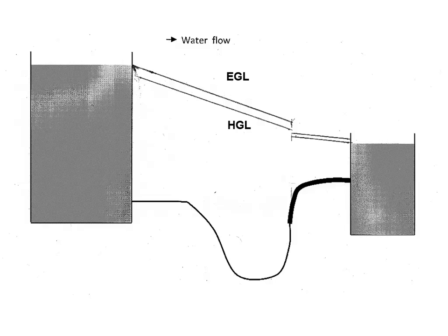Well, there should be at least a little change in drop. It doesn't necessarily have to be as big as mine, but to be strictly correct, we do have a sudden expansion there. So there is going to be some energy loss due to that expansion. So there should be some sort of a drop to show that. If it was gradual, then it would be less than the drop that's shown there. It would just be one solid line. Yeah. Right.